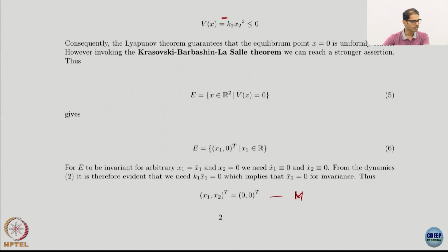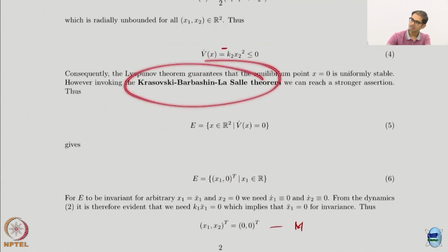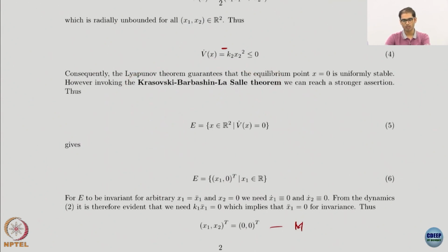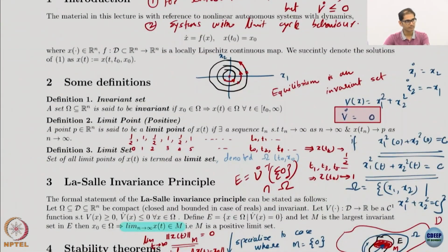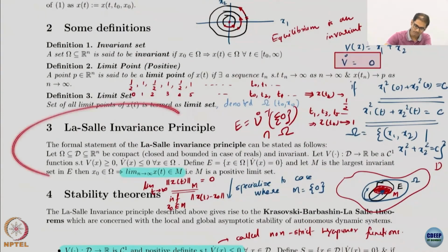I am not sure if we will have time, but there is also what adaptive control folks use, the notion of Barbalat's lemma. It is a different way of doing this, compared to Barbashin-Krasovskii-LaSalle, which you might find easier to use, and it can be used for time varying systems also, okay. Here you can't use these results in this form for time varying systems. But Barbalat's lemma also cannot be used for the multiple equilibria case. So, the general LaSalle invariance principle is a very powerful result. You can't get multiple equilibria type results from typically any other method, okay, not easy.